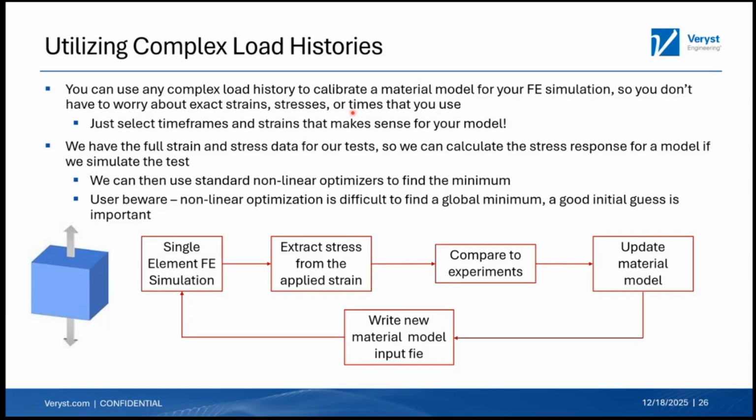But the advantage here is that with these, and if you use this workflow, you can utilize those complex load histories that I had. The idea is very simple. We're going to do a single element finite element simulation, and it's going to be a unit cube, and we're going to apply our displacements that we did in the test. So if we loaded it up and held and unloaded and all that, we measured that, we know what it is, so we can do that.